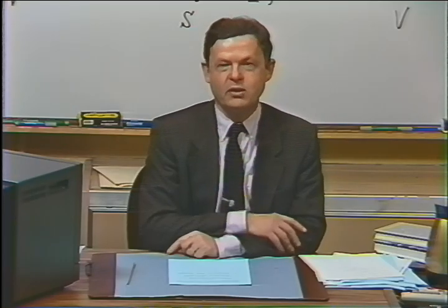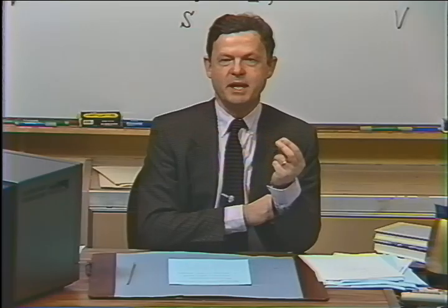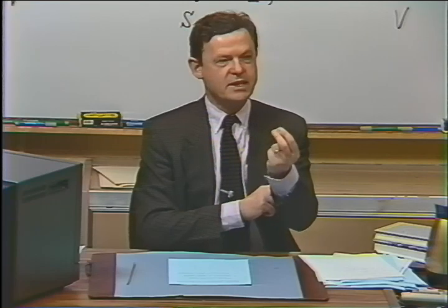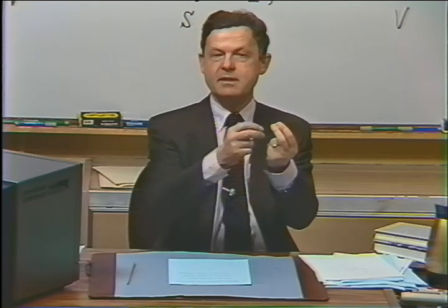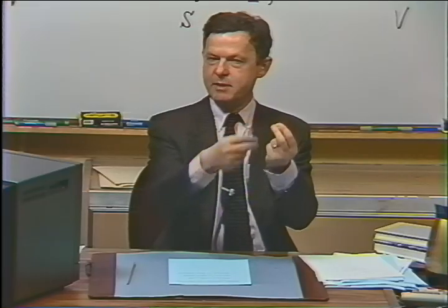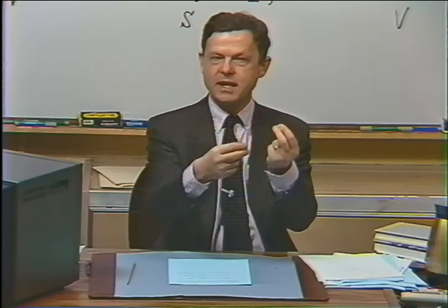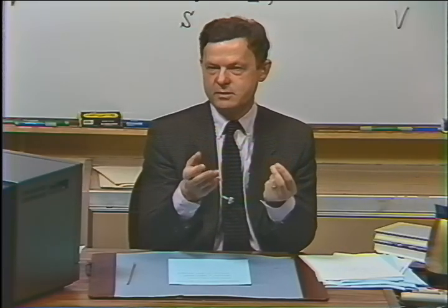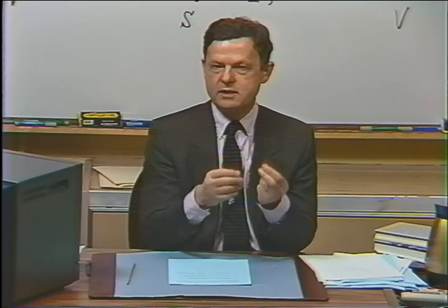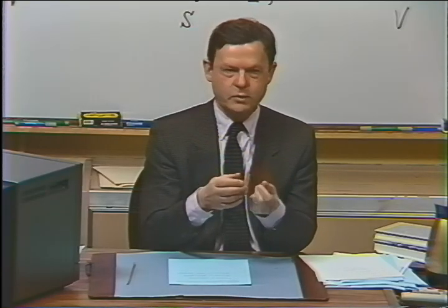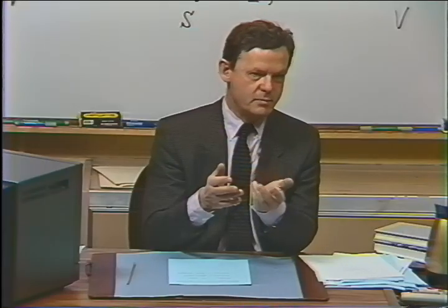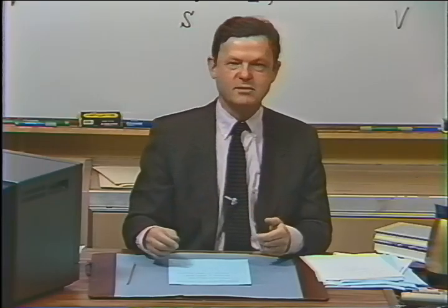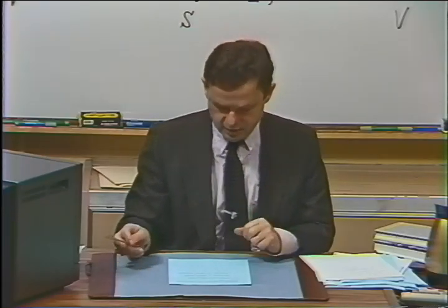Note, in an inhomogeneous flow, you would have a rate of deformation as a function of position. So your material element of interest might be subjected to a higher rate of deformation than the neighboring element. And then some gradients are coming up in the flow, and those gradients are assumed to be negligible when formulating an equation for the stress. Now, this is the so-called simple fluid assumption. All fluids which behave like that are called simple fluids. And there has not been found a case where this simple fluid assumption has been contradicted.